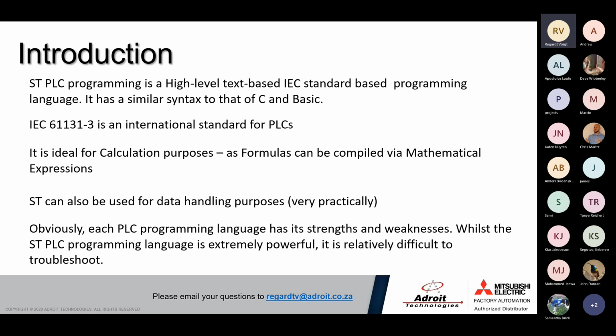A weakness for structured text would be the relative difficulty in troubleshooting due to the lack of the visual aspect you would have for function blocks, ladder diagrams and sequential flowcharts. Another aspect is that it can be used in conjunction with the other 4 IEC standard languages. You don't have to write your PLC program exclusively with structured text, only certain parts of it where you require it. That's the advantage of the IEC standard PLC programming languages.